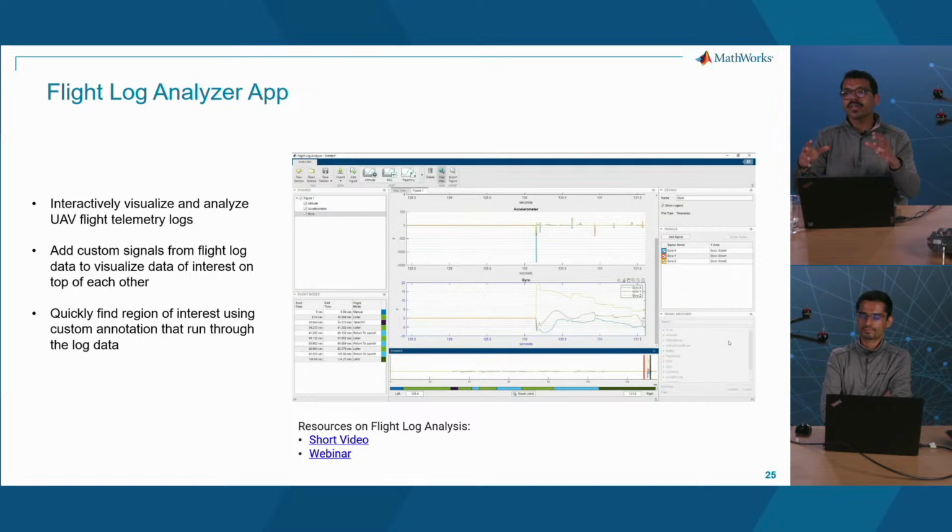And then once you set this up, you can actually save that session and forward that directly to someone else, and it'll open exactly how you were looking at it. So they don't have to fudge about recreating the plots or pulling in data. They just have to open the session, load the log file in, and they'll immediately see what you were looking at.